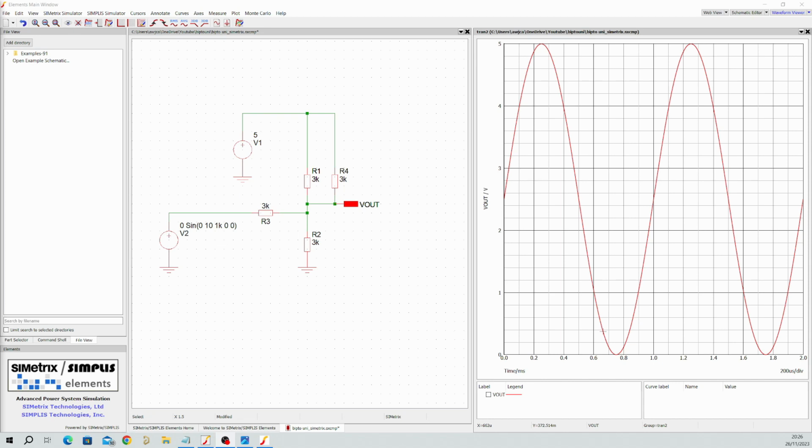Also, if you're going to do any rework task, so you get a unit back from the field that's been in service for 5-10 years, and for some reason you have to replace part of the network, then it's generally best practice to replace all the parts of that network.